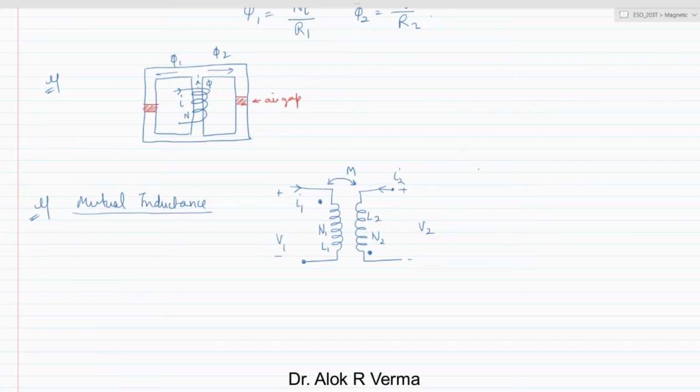If you are given K, like the coupling coefficient, right? If K is given, which is nothing but the coupling coefficient, K is a value from 0 to 1, okay. And if you want to calculate the mutual inductance from given K, M is nothing but K times root of L1 L2. Suppose here in this case K is 0.5, then the square root of L1 into L2, times 0.5, will be M. But if M is given directly, you can use it.